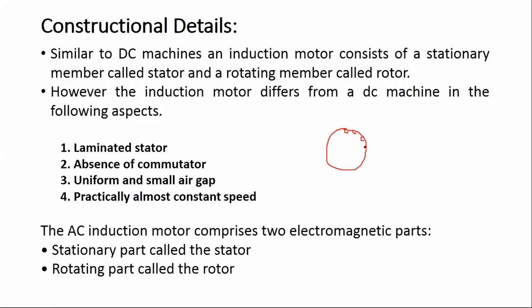These slots are used to put conductors, and conductors means winding, the armature winding basically, and then the armature winding is connected in certain formations, wave formation or lap formation, and this center part is, let us say, the space for the shaft, and then we have the outer stator part. The stator part has pole shoes basically mounted into it from inside the wall of the stator, right?